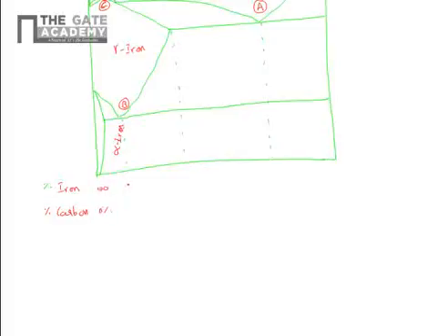If you go here, iron is 99%, but we will show only carbon, 0.83% at this point. At this point it is 2%, here it is 4%, here it is 6.67, approximate values.